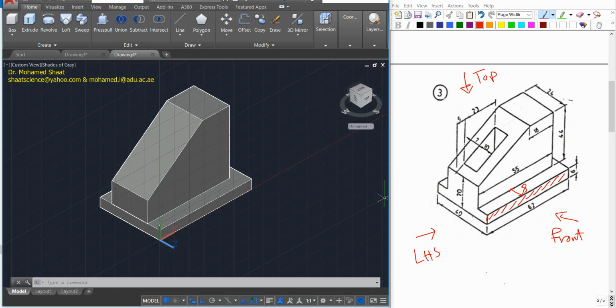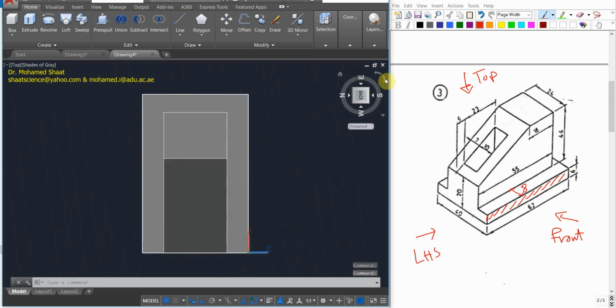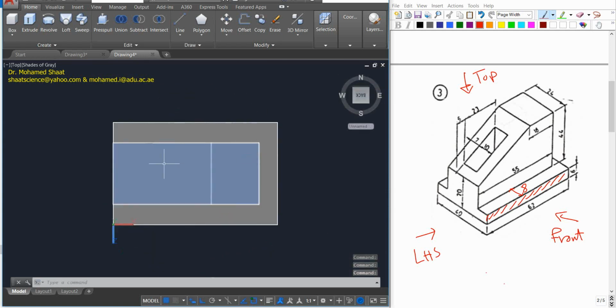So the question is how we can do it. We can simply do it by extrusion. For example, if we look at the top view of the shape, let us give it an orientation to be oriented the same direction as here. Okay, so this is a very simple shape to create actually. Your objective is just to draw a two-dimensional rectangular shape here, and then extrude it down in this direction, penetrating inside the shape.